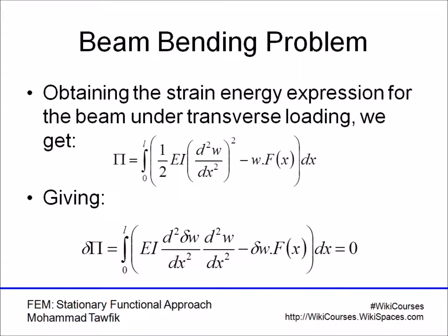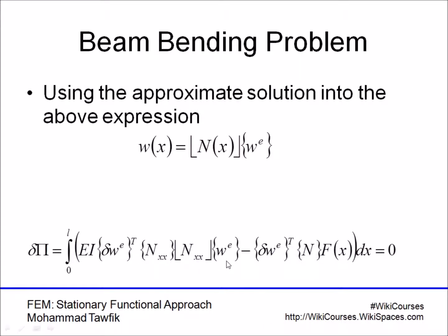If we perform the integration by parts on this term twice, we will get the boundary terms. I'm not going to go through that here, but we end up with the second derivative, the modulus of elasticity multiplied by the second moment of area, and we replace w and the variation of w by the shape functions that we have here.